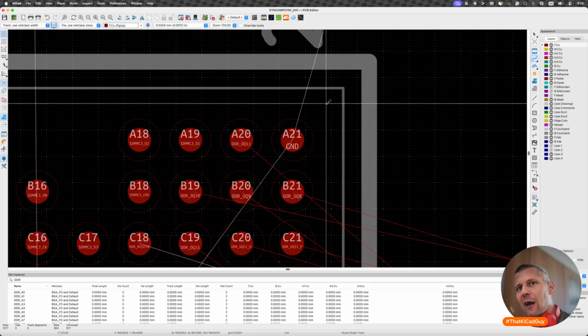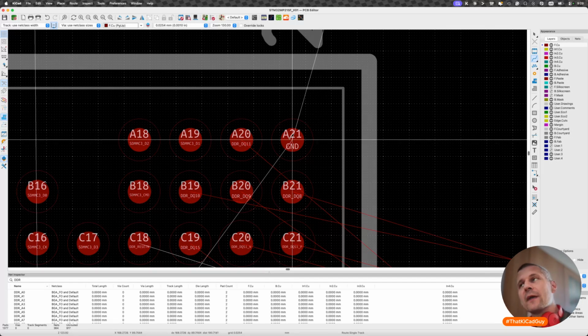The vias will be covered. In the case we copper pour the ground plane on the top layer, the via would be completely invisible because it's epoxy filled and covered, so the copper plating on top will cover the via completely. But it's not our case, because we won't pour copper on the top layer.